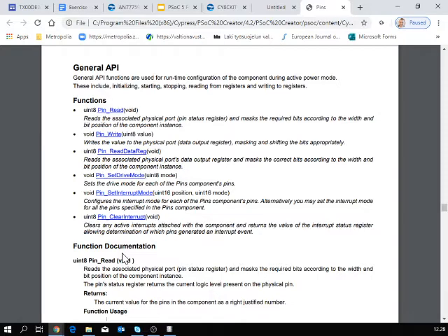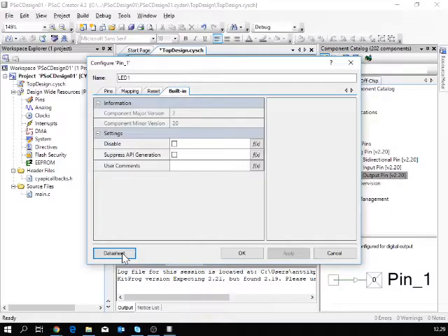It takes a lot of magic out of the interrupt. And then clear interrupt. Well, this is an ARM processor, so after serving the interrupt request, you also need to clear the interrupt. Also the function documentation is here, with an explanation of the side effects.